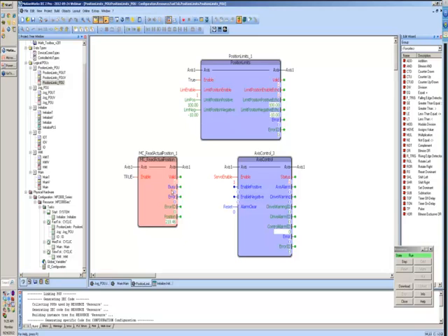There we go. So even though our limit position is enabled, and our position is greater than our positive position limit, because we're actually commanding it to move in the negative direction, it's going to allow that. And once it gets down to its negative position limit of -10, you'll see it comes to a stop. And it comes to a stop using the maximum deceleration that the drive can provide.